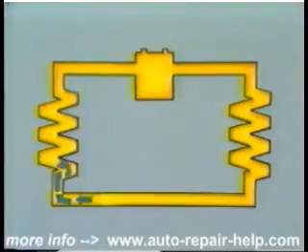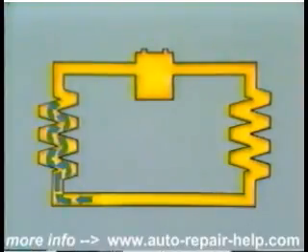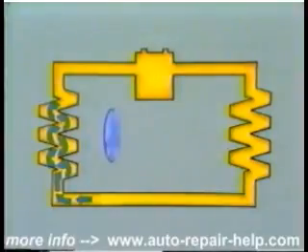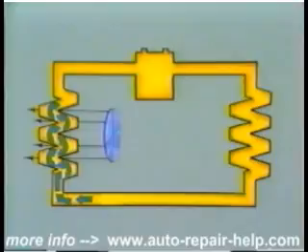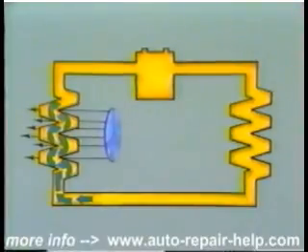Freon, in liquid form, is passed through the refrigerant tubes of the evaporator. When air is forced past the fins of these tubes, the R12 absorbs some of the heat from the air. In the process, the liquid refrigerant is changed to vapor, and the air serves to cool the passenger compartment of the vehicle.